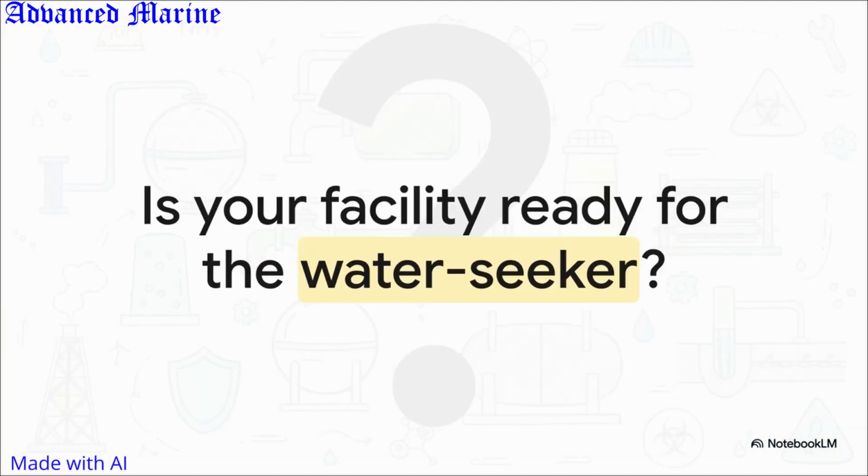So, what does this all mean for us? Ammonia is a powerful, demanding chemical that plays by its own strict rules. It seeks water, it dramatically spikes the pH, and it will destroy unprepared metals and elastomers. But as we've seen today, with precisely selected FH36 steel, passivated SUS 316L pipelines, molybdenum-reinforced valves, and specialized graphite seals, it absolutely can be contained. As global industries, especially the maritime sector, rapidly turn to ammonia as a zero-carbon future fuel, the stakes for getting this engineering right have literally never been higher.